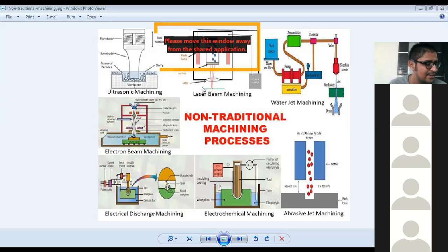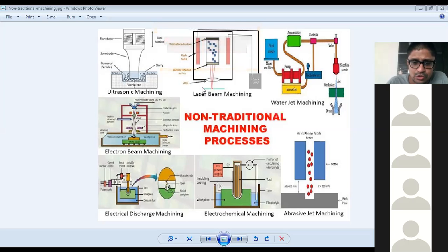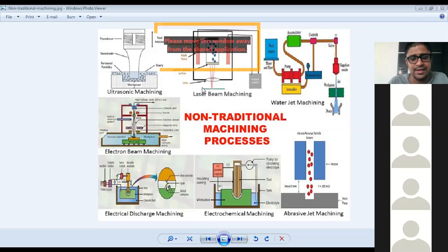So as you have mentioned, in some materials there is an issue of absorptivity, but as per my knowledge, there are some commercial lasers now available which can take care of this absorptivity. It depends on the type of laser you use, but yes, absorptivity is an issue, especially for pure materials which are not alloys. In that case, absorptivity may play a vital role.